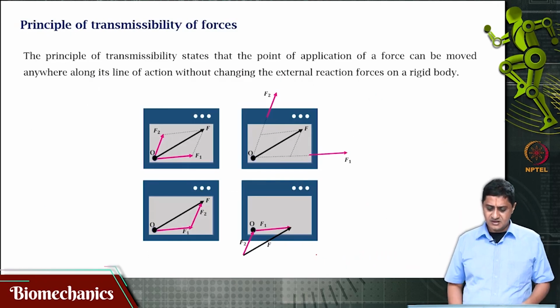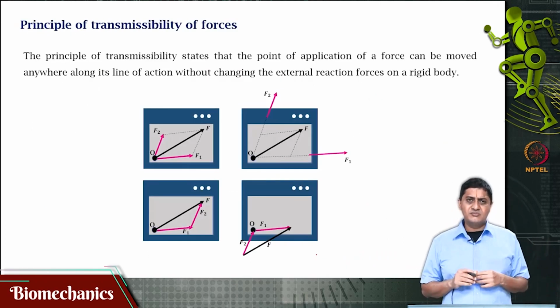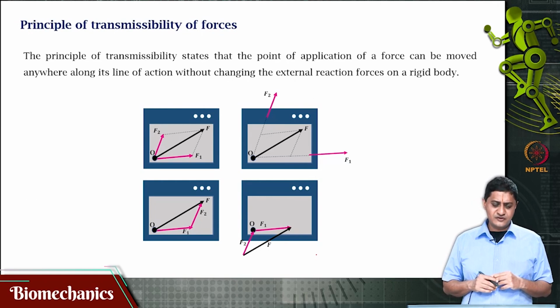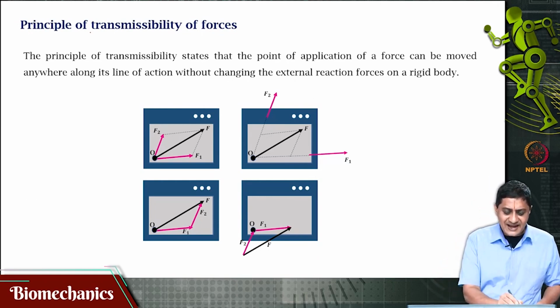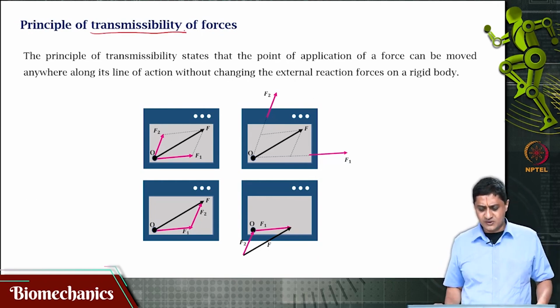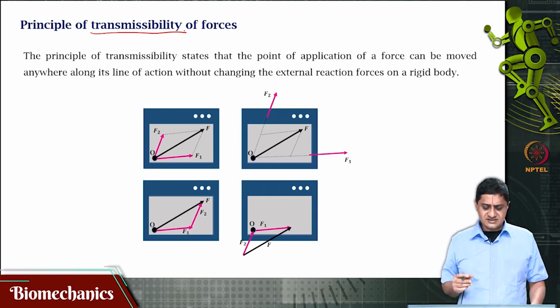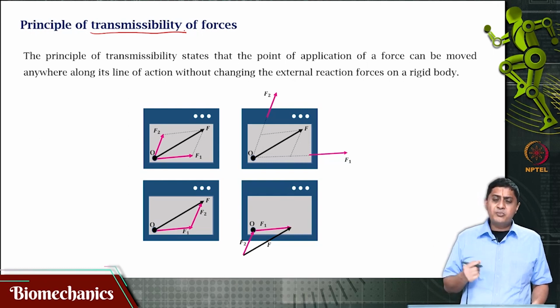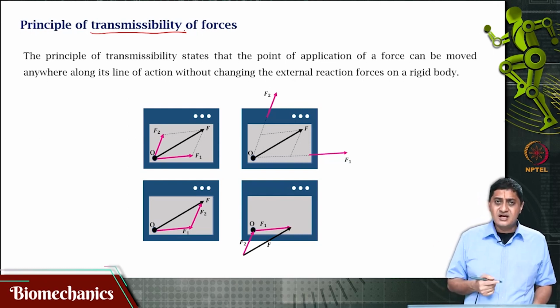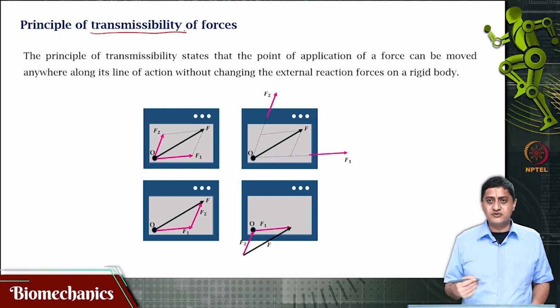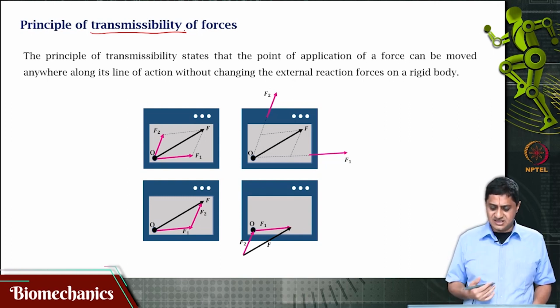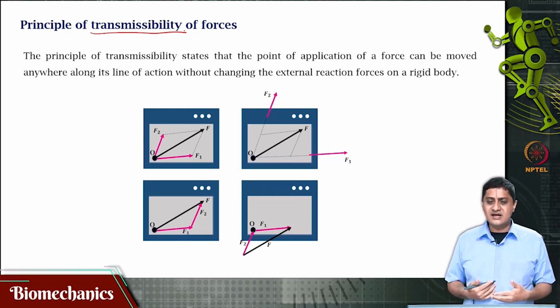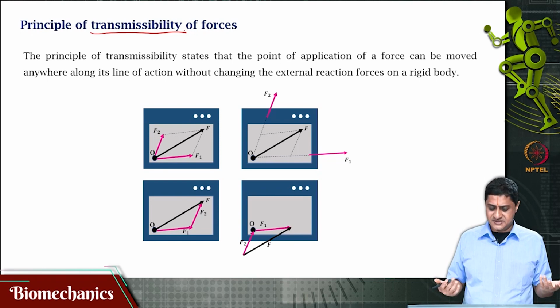Okay. One important principle while dealing with forces is the principle of transmissibility of forces. What is this? This is the idea that I could move the point of application of force along the line of action of force without changing any other factor in the analysis.